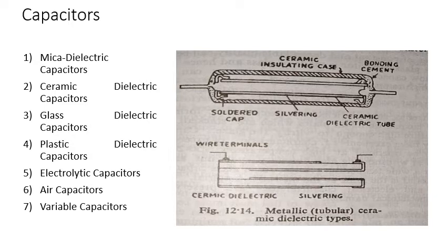So the power factor, which is independent of frequency, is generally around 0.002, and its low dielectric absorption enables it to be used in long time constant circuits. So the capacitance stability should be of the order of 0.5% and permittivity is 2.5.